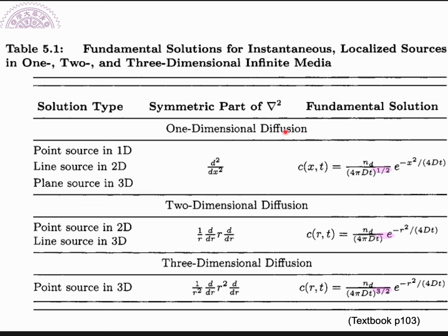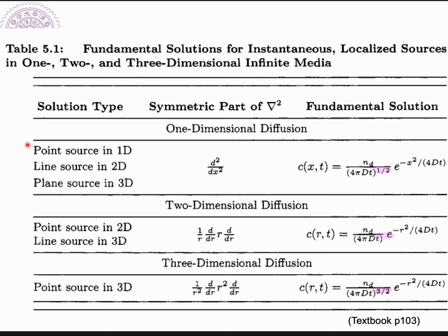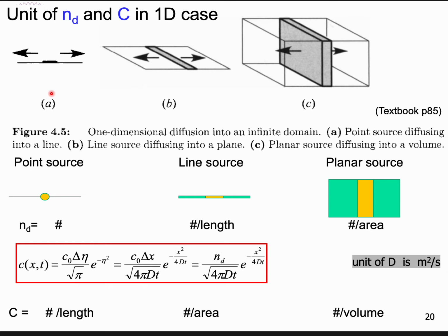Okay, so what are they? Instead of just using a description here, I grabbed some pictures to demonstrate. This also belongs to the one-dimensional diffusion case. This one is the one we just introduced, right? You have a planar diffusion source in your matrix, and diffusion happens. The diffusion source diffuses toward the left-hand side or right-hand side, so the distribution is mainly along one dimension. So we call this a one-dimensional diffusion case.